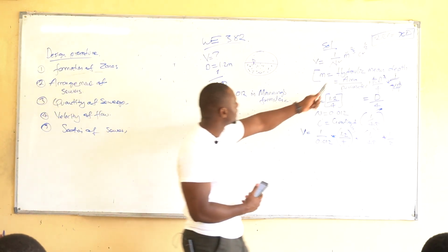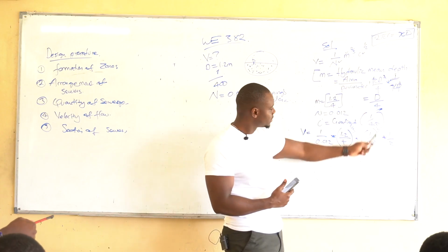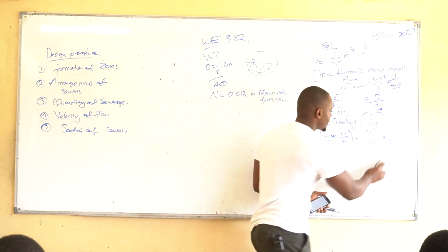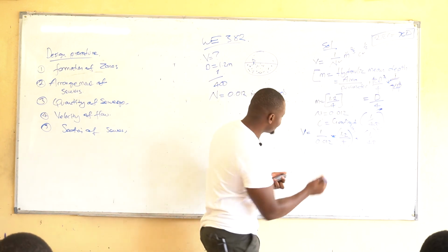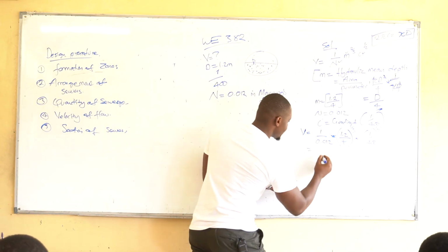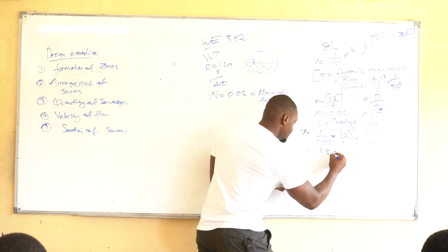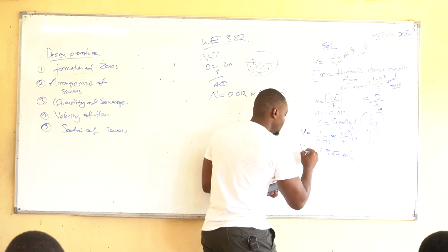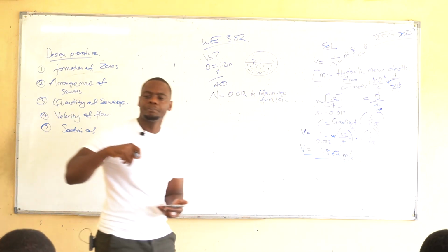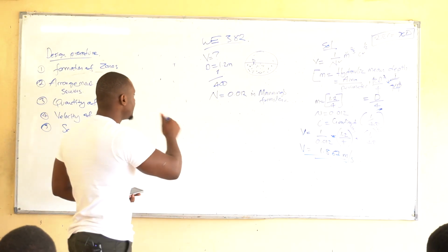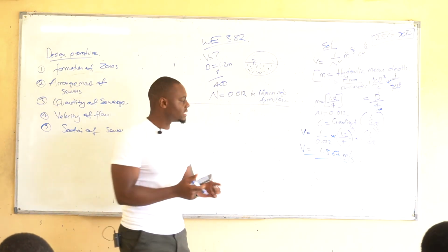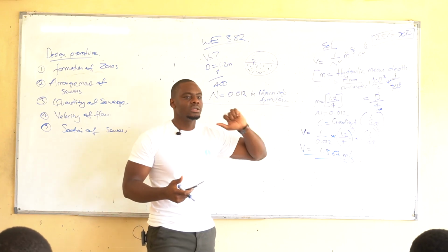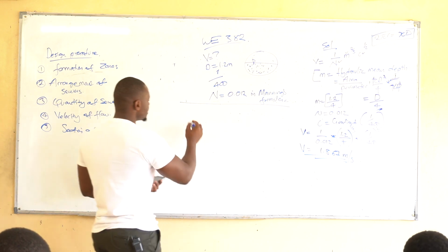Which one? Like here? No, you don't put it here. So without the half, what value are we getting here? According to this, it says 1.867 meters per second. So this is your velocity. The half comes in really important when someone says, if you have your velocity, can you now give me the discharge through that sewer? What's the formula for a discharge?